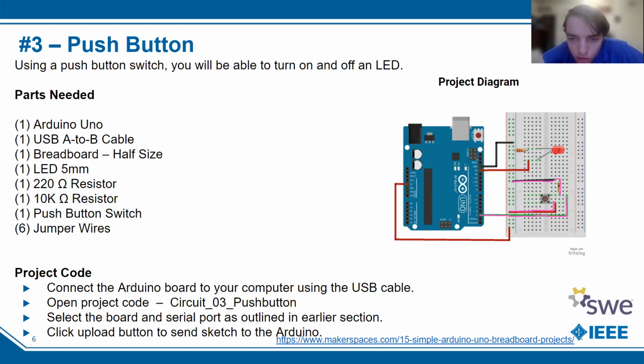And so that signal is going to be sent back to the Arduino. The reason we had a power connected here was just so we had a source going to that push button so it could actually read the signal. So when we pressed it, there was some supply given, so then it can send that signal back to the Arduino. And then that signal coming back from the Arduino is what's going to drive the LED here and make the LED turn on.